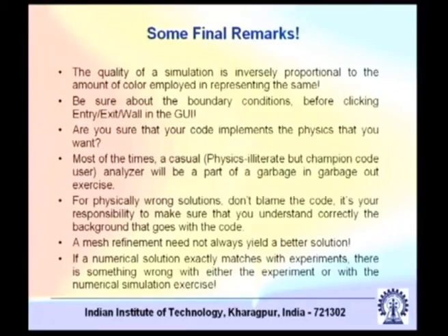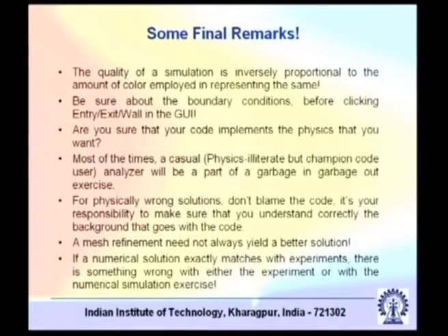So if you are interested to solve a rarefied gas dynamics problem, then in that case continuum equations may not be valid, and you may require molecular simulation or mesoscopic simulation; several other types of simulations are there. Now there you are forcefully trying to use the standard Navier-Stokes equation without any alteration in the boundary condition, and you are expecting that your code will give you the correct result. That is not what you are going to look for.